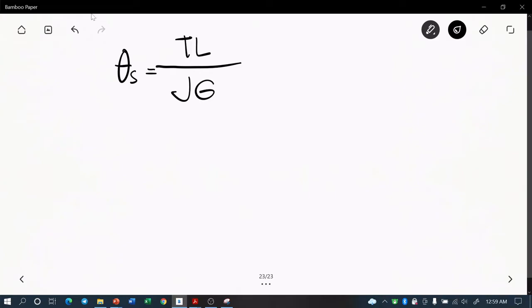Okay, so the torque is already known. So this is 276.32 inch-kips. We're going to indicate here with a check mark. So the length is given. In the problem, in the third requirement, it is stated there that the length of the shaft is 10 feet. Okay, and we have an expression for the centroidal polar moment of inertia.